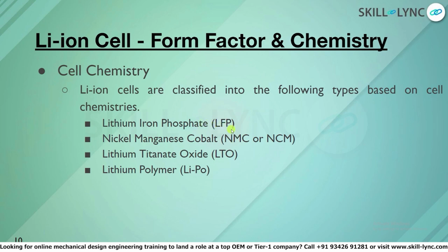For example, each chemistry has a different voltage window, and this combination of materials in a cathode also determines the energy density, the C rates, and the life cycles of the cell, etc. So these are the initial cathode components which play a vital role in selection of a cell as per the application. For example, LFP, lithium iron phosphate, has higher life cycles when compared to NMC, but it cannot give higher C rates when compared to NMC.